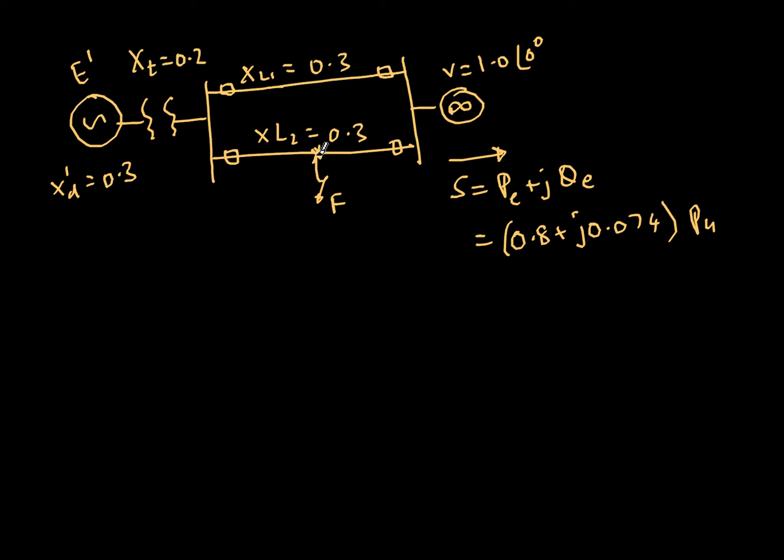Then when the fault is cleared, this circuit breaker and this circuit breaker are open circuited, so this entire line is isolated, and now the transmission network is only one single line, so we still have some power flow going on. So the maximum power transfer limits before the fault, during the fault, and after the fault will be different. That's what we'll have to calculate in this.